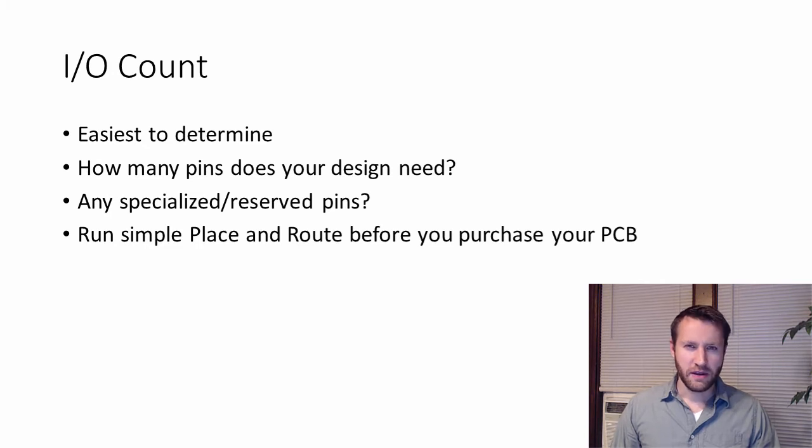And the more complicated your design is, the more I emphasize this. If you have a really simple design, it's less important, but if you have like SerDes, which are like high-speed serial deserializer transceivers, if you have SD memory, if you have really fast I/O, those are things you really want to test out before you purchase your printed circuit board to make sure that you're actually choosing the right FPGA for your needs.